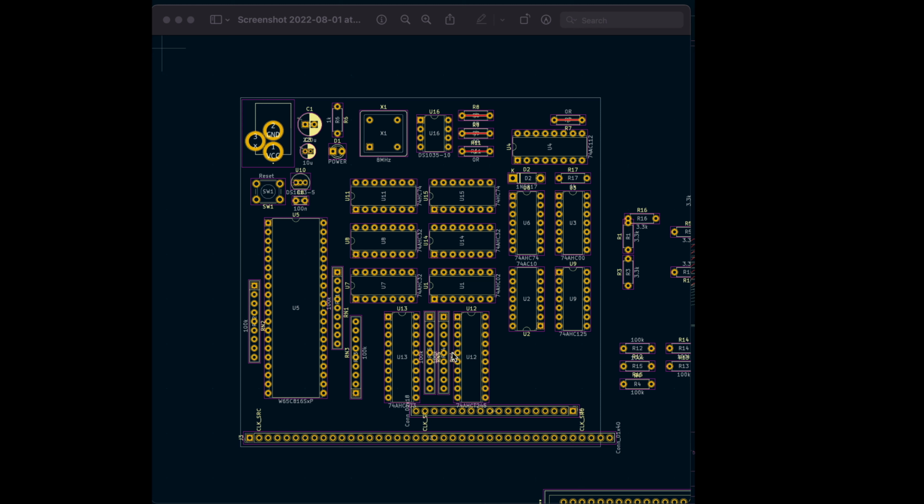Okay, so I've been trying a few designs off camera just to get a feel for the components and how they fit together. This first one was an attempt at making everything fit into a 100mm by 100mm board. It kind of fit, but it was very tight, and I couldn't see a solution for hooking up to the breadboard with all the signals that we needed. So I decided to scrap it. I'll probably go back to this format later when we have CPLDs taking off all those ICs from the board.